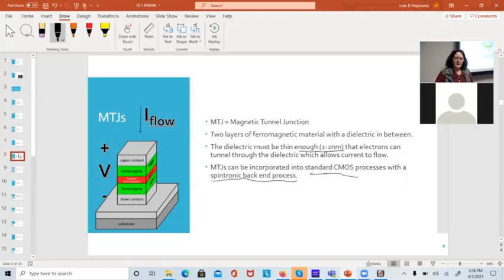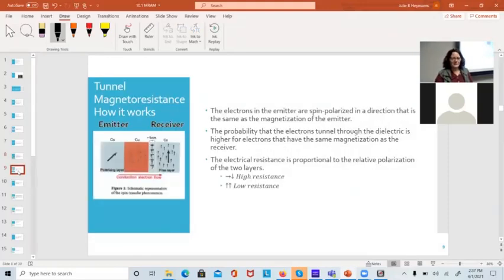Okay, and depending upon whether I have a higher resistance, if I force current into this, if I have a higher resistance, I will get a higher voltage. A lower resistance will give me a lower voltage. If I force voltage across it, I can measure current and determine what the resistance is. This is what we do a lot of in the lab. It just comes down to V equals IR. Just measure things very accurately. Ohm's law.